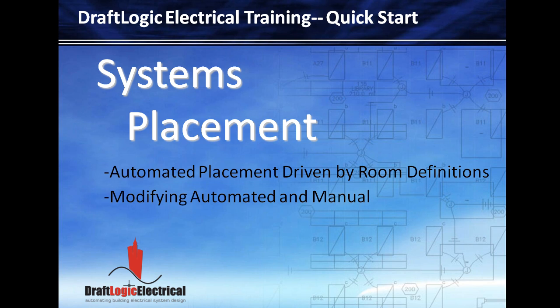In the systems placement phase of work, you can use DraftLogic Electrical's automation to automatically place certain types of devices. And of course, you can manually place devices or modify those that were automatically placed. DraftLogic Electrical provides a variety of tools to help you in both scenarios. Once you're done placing your systems, regardless of how the devices made it to where they were, as long as you have used the standard DraftLogic Electrical blocks, DraftLogic Electrical sees all placements as equal. There's no differentiation between those that were automatically placed or manually placed.